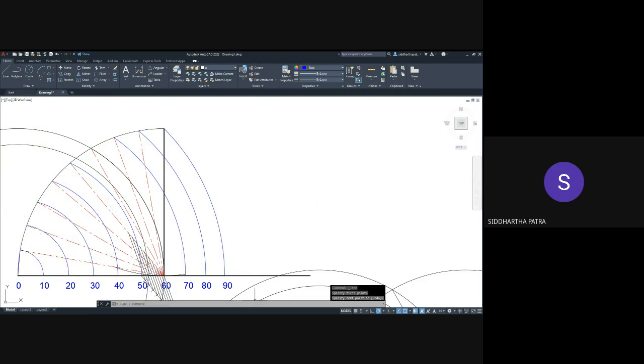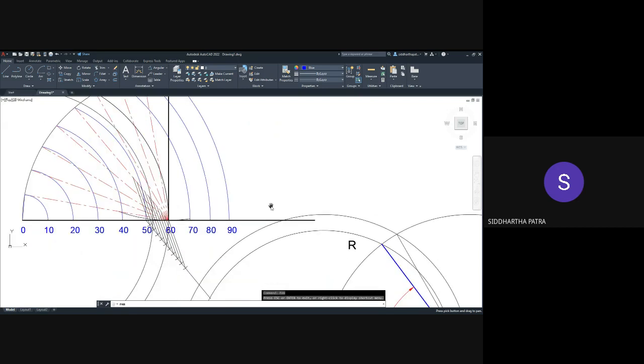So earlier you did an approximation by trisecting an angle, okay, which is not 90-degree or 180-degree. Now you are willing to do another approximation. For example, now you are asked to draw an angle which is like 65 degrees. So all you have to do is divide the span between 60 to 70 degrees into required number of segments. If it is 65 degrees, only two segments would suffice. But then you are taking the division uniformly.